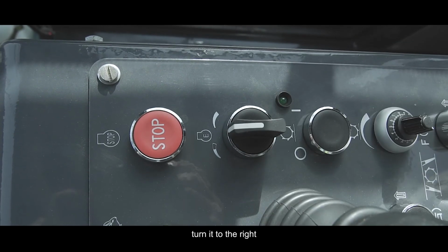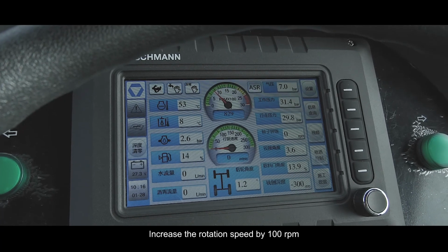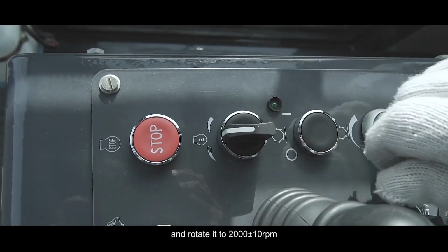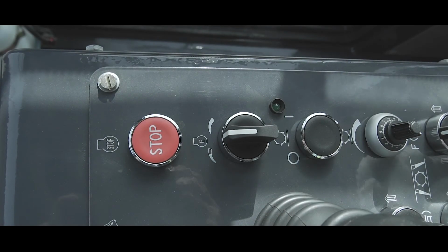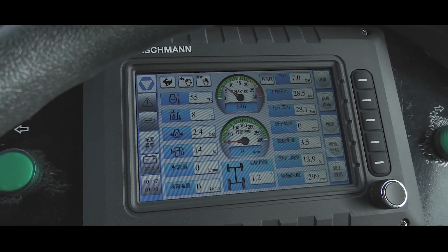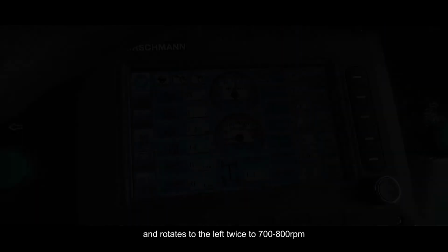Turn it to the right. Increase the rotation speed by 100 RPM. Rotate it twice to the right and rotate it to 2000 plus or minus 10 RPM. Rotate it once to the left, and the speed drops by 100 revolutions. Rotate to the left twice to 700 to 800 RPM.